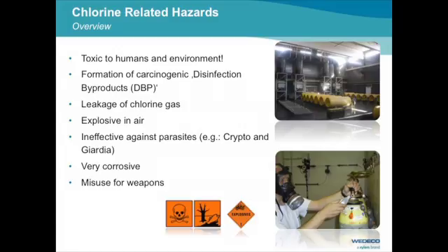That was also the time when a very extensive guidance manual on UV system design was established in order to make it a really safe alternative. And last but not least, chlorine is a very corrosive agent, so you need to be aware of that when designing all the piping and distribution services.